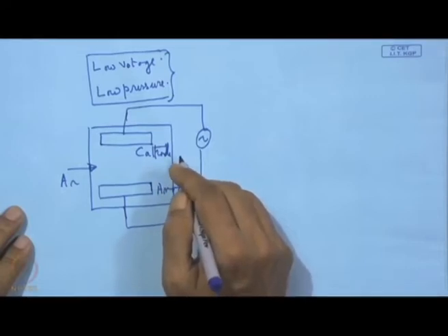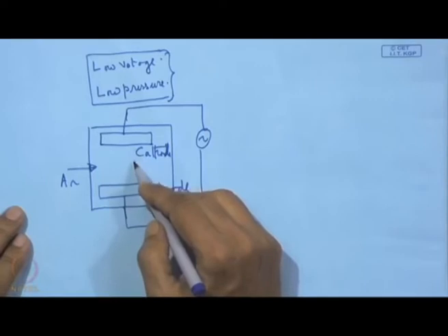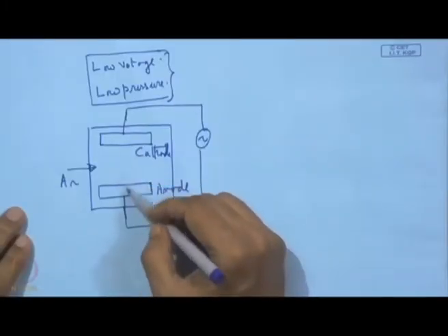That means we can immediately understand that these secondary electrons, which become primary electrons in this plasma volume, are not properly utilized if they have just a directional flow and finally strike the anode. It can be one anode plate or it can be the wall of the chamber which can also serve as anode. However, when it is an alternating supply, an alternating field, in that case these electrons will keep on oscillating.